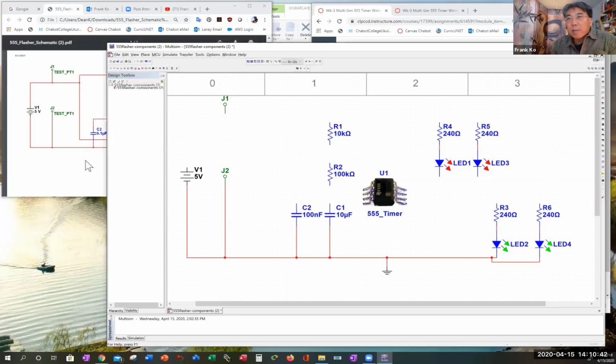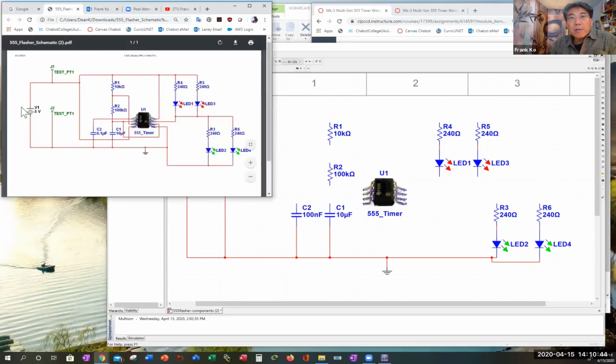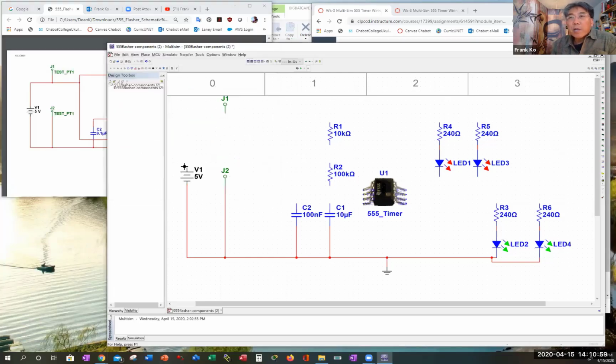Let's see what's happening on the top side of the circuit. On the top side of the circuit, I've got positive 5 volts coming out, and it's got to connect to the top of this voltage series resistor arrangement, and then it connects to 4 and 5. So I'm going to do that here. I'm going to take my voltage source. Again, this changes from an arrowhead to a black dot. Come up here and bring this over to here and connect